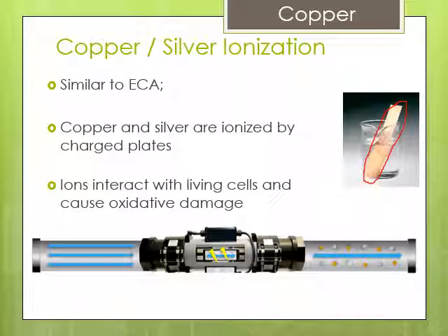But essentially with copper and silver, by applying electricity, the atoms come off the plate and go into solution. This is kind of how you copper plate something, right? You apply a voltage to the copper and then you ground the object that you want to copper plate, and the copper ions will move from the copper over onto whatever object you want to copper plate.